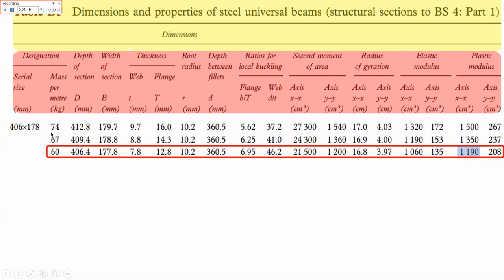Remember, you're also looking at the cost. So you don't want to take a beam section which is heavier. Remember, steel is measured in kg. So if you take a steel section which is higher, it will be expensive. So we have to balance between the cost and the design requirements. So in my case, I hope this beam will be adequate, but we are going to check that.